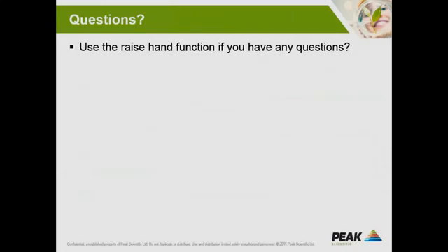I guess, Mr. Dixit. Yeah, I'll just take the next question from Mr. Narasimha Prasad, who says, how many GCs can be connected to one generator, and I guess he's speaking about the zero air. I've unmuted Mr. Prasad. Okay, to the zero air, typically an FID will be using between 300 and 450 cc's